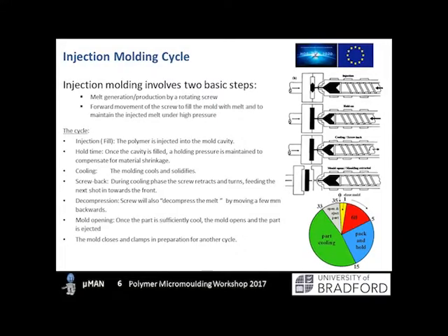But if we stayed in that constant velocity control and filled the mould cavity, we would get a sudden increase in pressure because the material has nowhere to flow anymore, and so there'll be a big spike in pressure, and that can in some cases cause damage to the tool. So what we actually do is part fill the cavity to about 99% full, and then we switch over the control of our screw from a velocity-controlled regime to a pressure-controlled regime, okay? So now we can no longer see these pressure spikes. We can impose a pressure limit on the filling phase of the process.